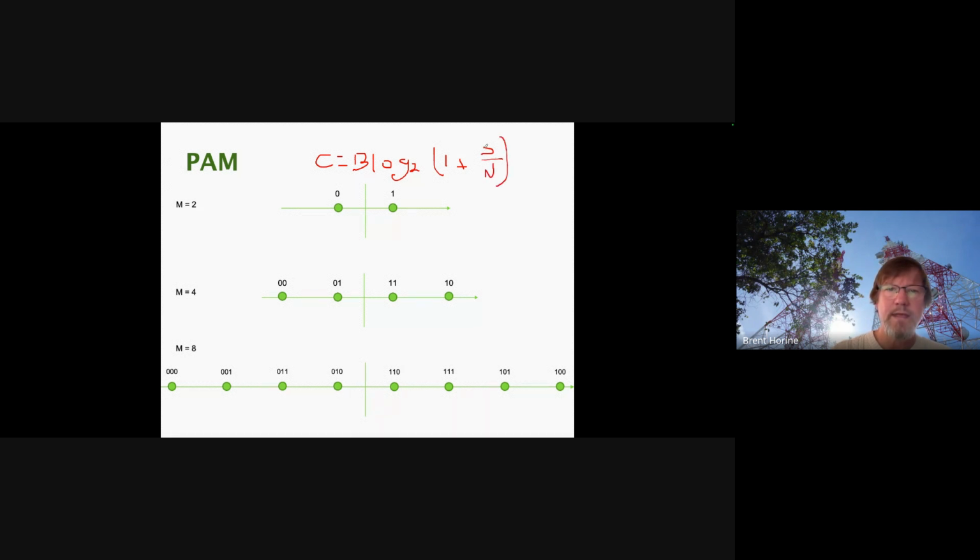So now if our signal can be strong enough relative to the noise, then we can go to a higher M, and now we can send 3 bits in the same period of time that it takes to send 1 bit, because the bandwidth here is going to be driven by your symbol rate, right?